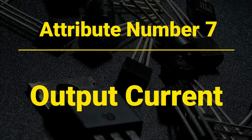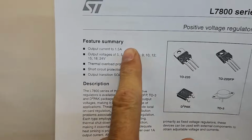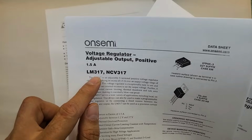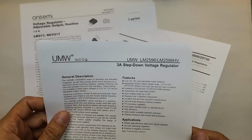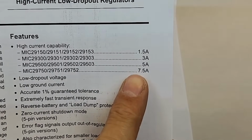Attribute number 7, output current. Output current is the amount of current that the regulator can safely provide. Look here, L7800 family can provide up to 1.5 amperes. LM317 can provide up to 1.5 amperes. LM2596 can provide up to 3 amperes, and MIC series can provide up to 7.5 amperes.